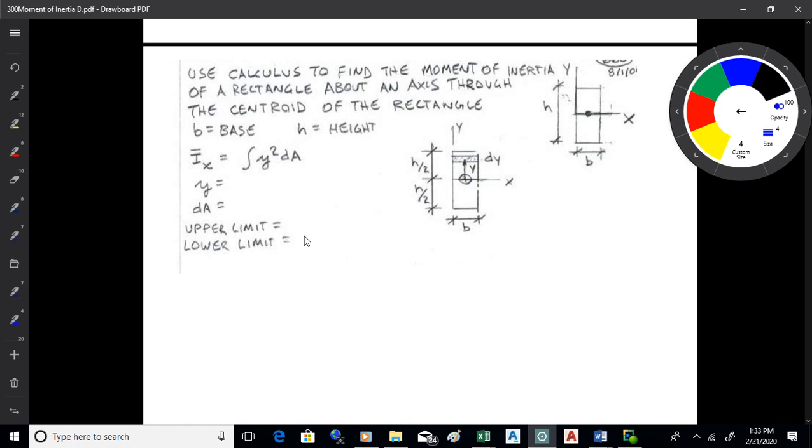All right, now the way I think about doing this would be to write a computer program. Let's find the moment of inertia of a standard rectangle that has a base b and a height h. Each time I do this, I need one discrete distance y, okay? I can't use dx's for this because dx's would cut across the shape like that, and I don't have a single y distance. So if I need a y distance, I need to use a dy, which would just be a small rectangle running across the beam. The distance from the x-axis to that dy would be essentially y. It's just how high it is.